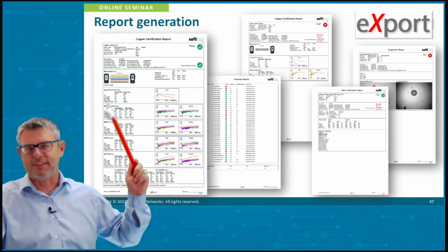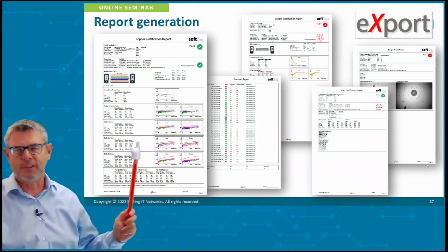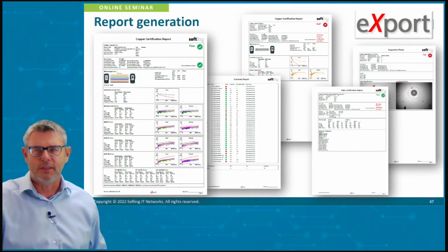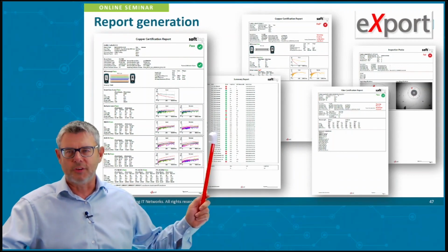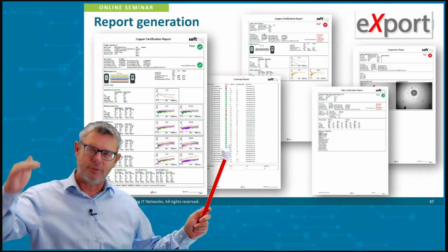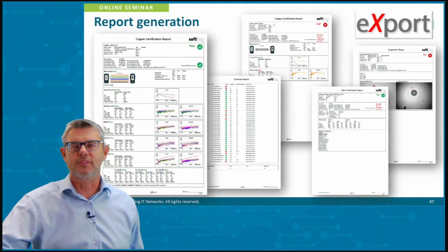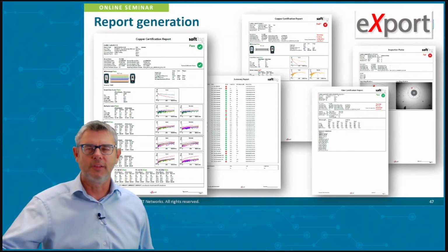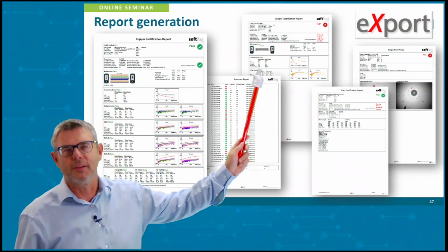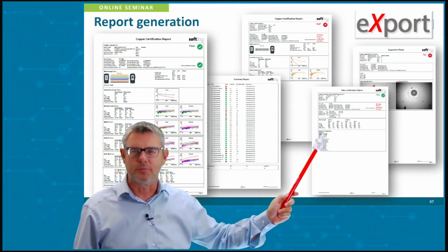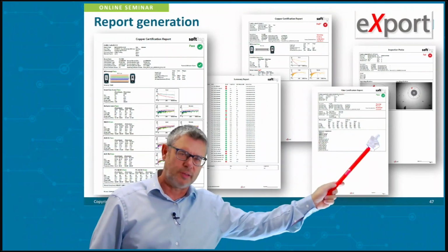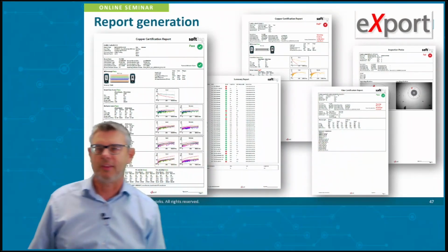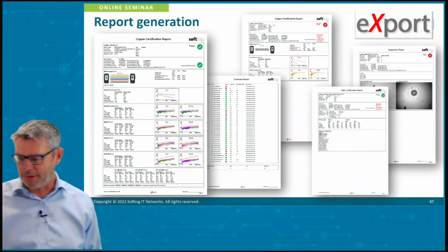This is the classical report for a certification run on an installation link. Here is a summary page, which you put on top of the other individual pages in a complete documentation, a sample of coax measurement, a sample of fiber optic, which we will see tomorrow in detail, plus fiber end face inspection, but that's, as I said, topic of tomorrow.